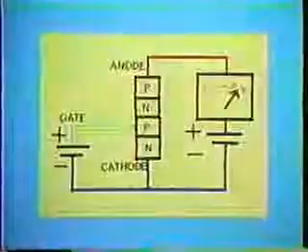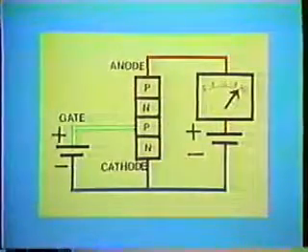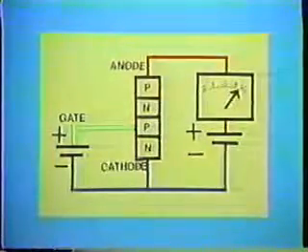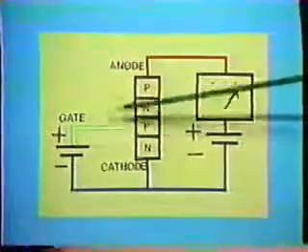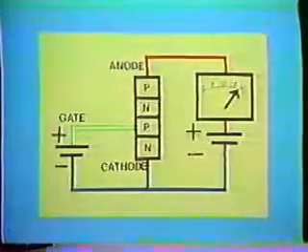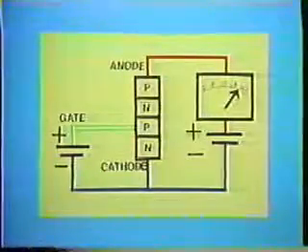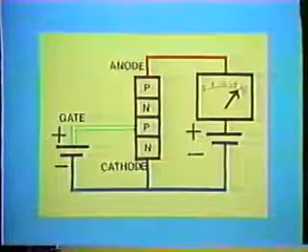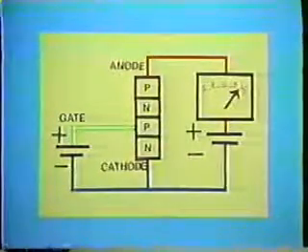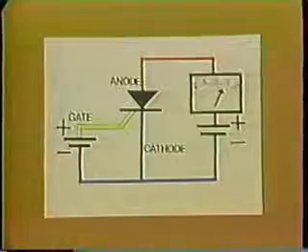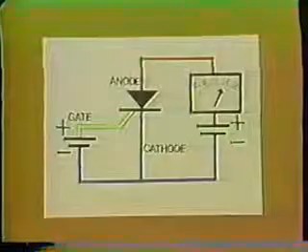Remember, in a transistor, the base current controlled the amount of current flowing through the transistor. However, once the SCR is conducting, or in other words, current flows through it, the gate cannot control the amount of current which flows, nor can the gate turn off the SCR. Thus, the gate of an SCR is not equivalent to the base of a transistor. We can now see that the SCR is not like a rectifier or a transistor, but is an entirely different device used for different purposes.